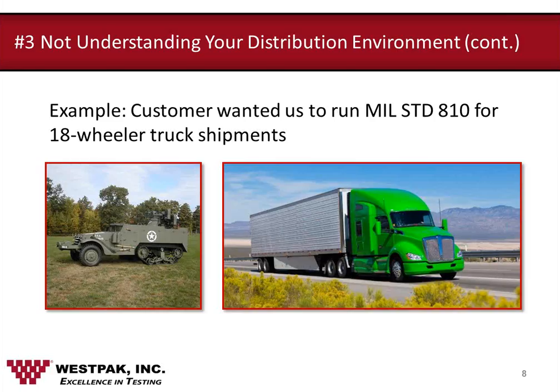If you want a more in-world realistic test, what you can do is run it through ISTA 3A and use the optional testing of vibration under vacuum, where there's a vacuum vessel placed on top of the vibration table, and then place the product in there, pull it to 14,000 feet, and then run the vibration while it's at vacuum to see if you're going to get holes at vacuum. Any more questions, Tim?